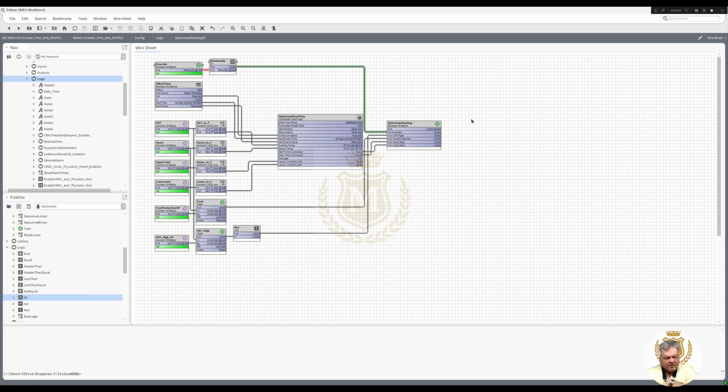So space temperature sensor and a set point to switch on and off the pumps, and then you probably want to control a valve, and again it's going to be controlled on the space temperature, or mainly, sorry, it's controlled on flow to the radiator system, or whatever system is there. I presume we could just put another block in there, duplicate, and we'll go for VT flow.